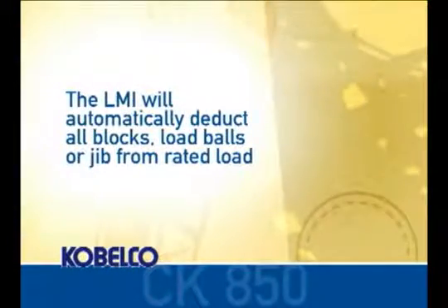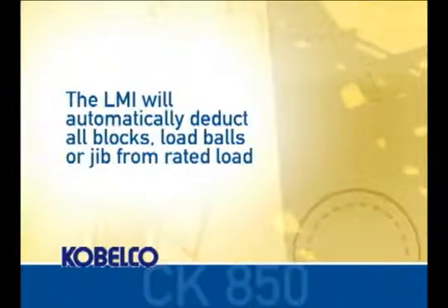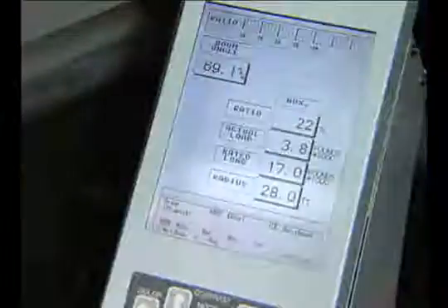The actual load is the present load on the load block or ball within a 2% error factor. The rated load is what the crane is able to pick at its present configuration. As an aid to the operator, the LMI will automatically deduct all blocks, load balls, or jib from rated load. The radius is the distance from the center rotation of the crane out to the load block.